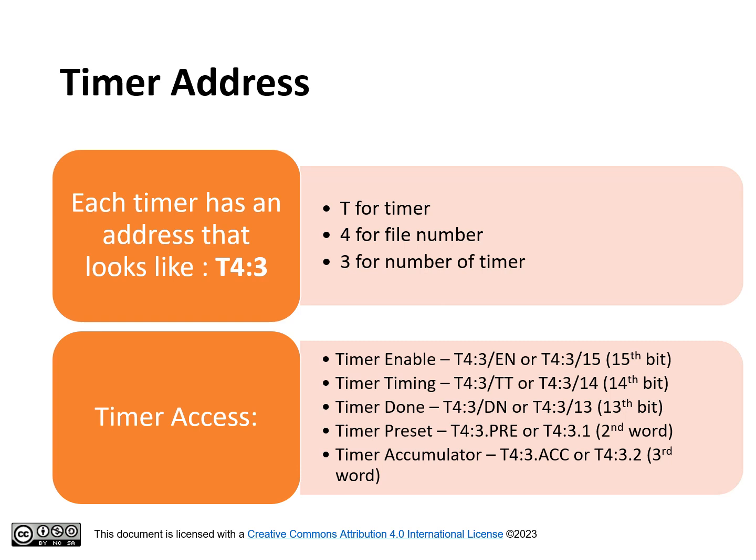In order to access the fields of this timer, the following addressing scheme is used: timer enabled, T4:3 EN or T4:3/15 on the 15th bit. Timer timing, T4:3 TT or T4:3/14 on the 14th bit.